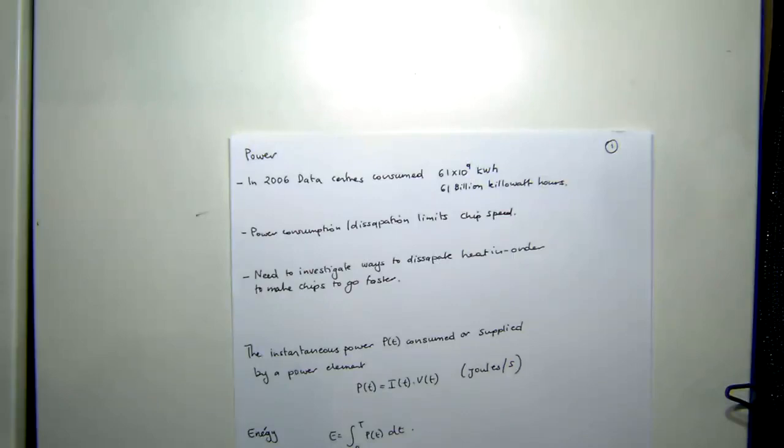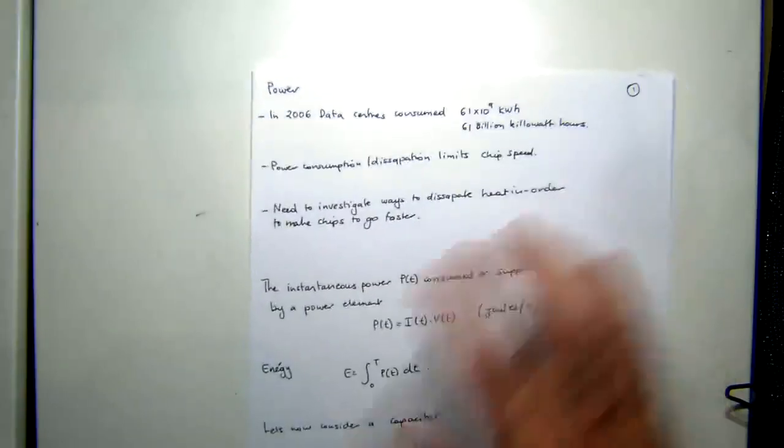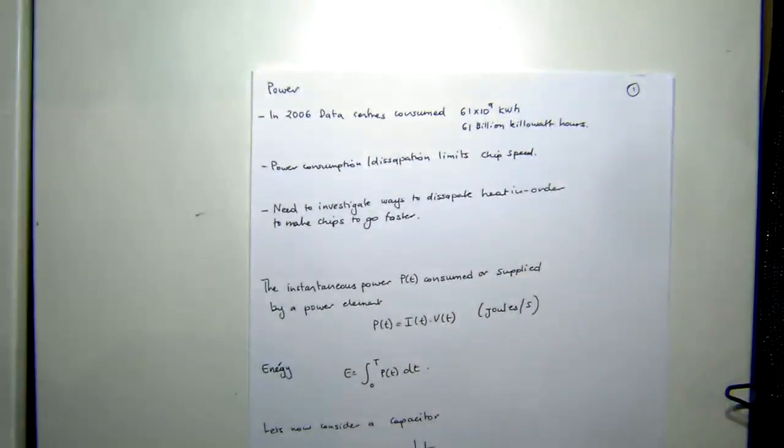But also, as your colleague has just pointed out, the chip itself gets hot, and all of a sudden you've got the N wells or the P wells, whatever. If it gets too hot, they start not being well defined any longer, and those wells are no longer wells anymore, and it just becomes this big mess, right? So the chip destroys itself. And that's one of the things that really limits the performance of chips, right?